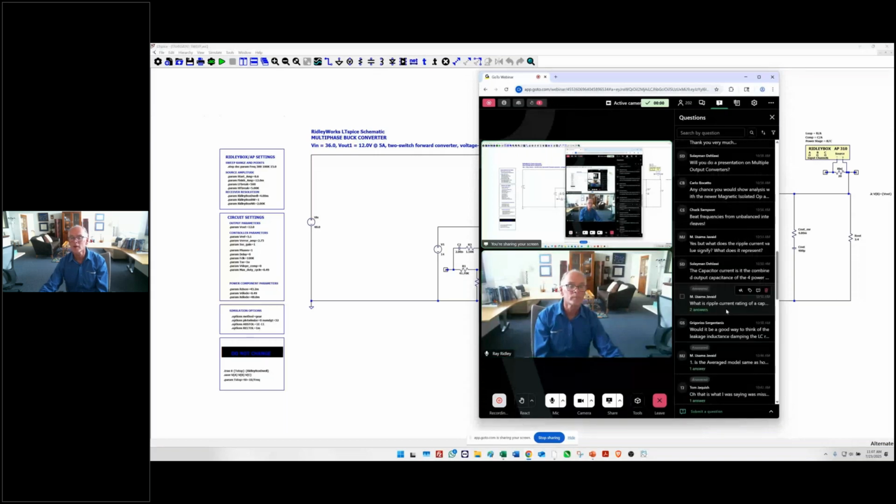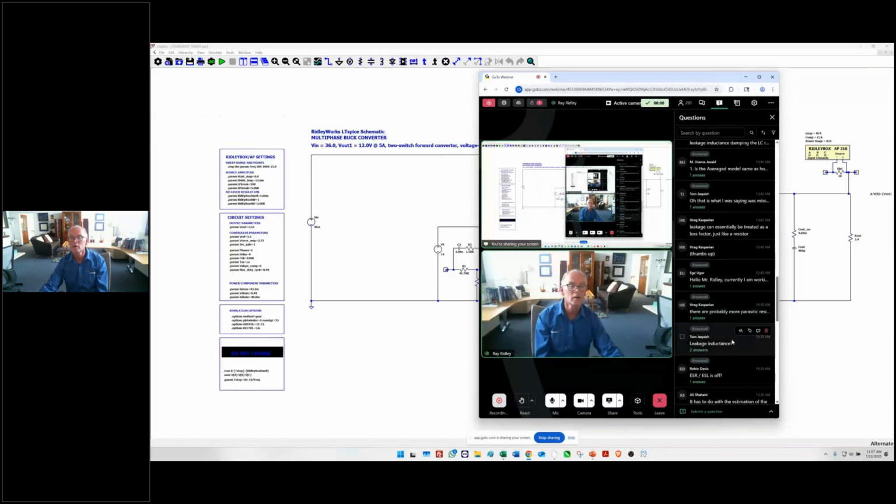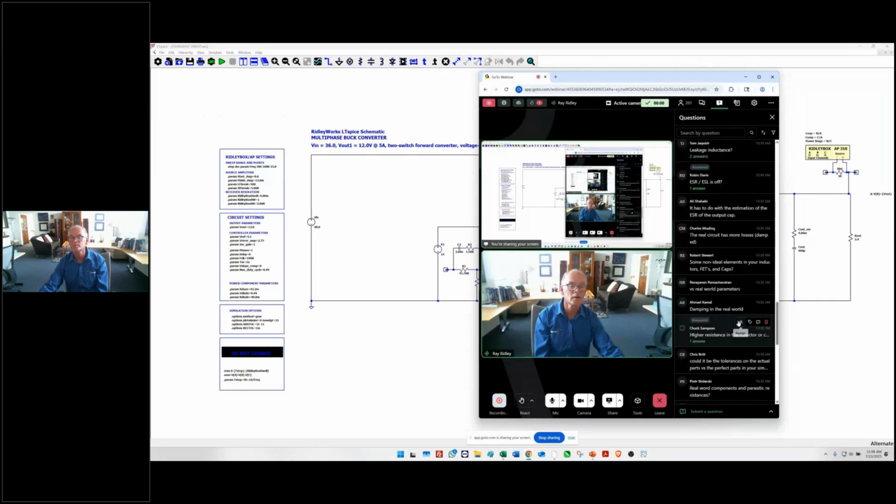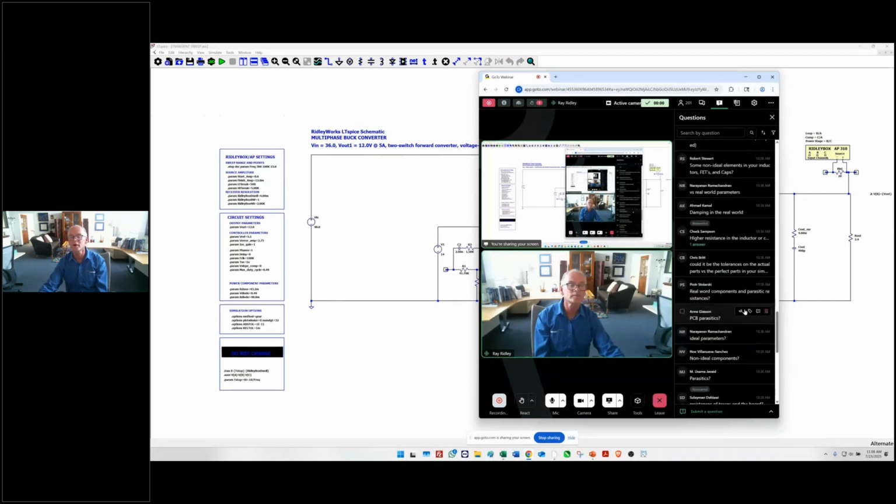Art, if you could turn on your microphone, do you see any questions I haven't answered? ESR, ESL is off. If you want to put that into the swept circuit model, be my guest. LTspice might not like it, but you can certainly include that. Is it the tolerance of the parts on the Q? I'm sorry, I missed these comments at the time. No, it's not that. As you saw, it was the leakage that causes that.